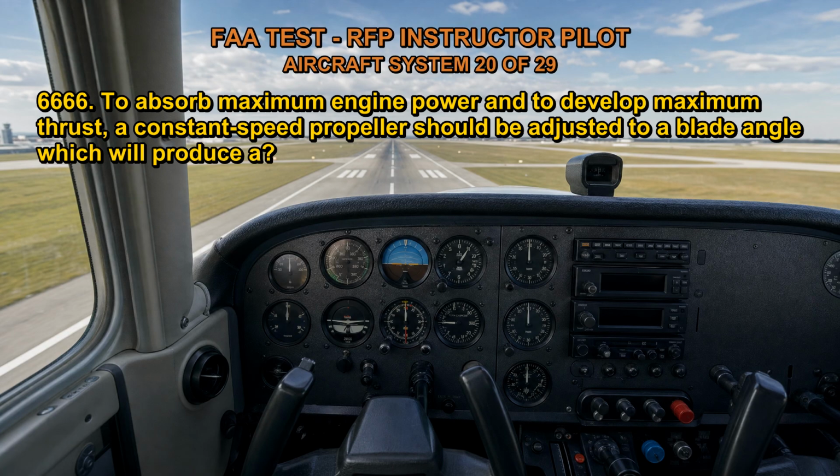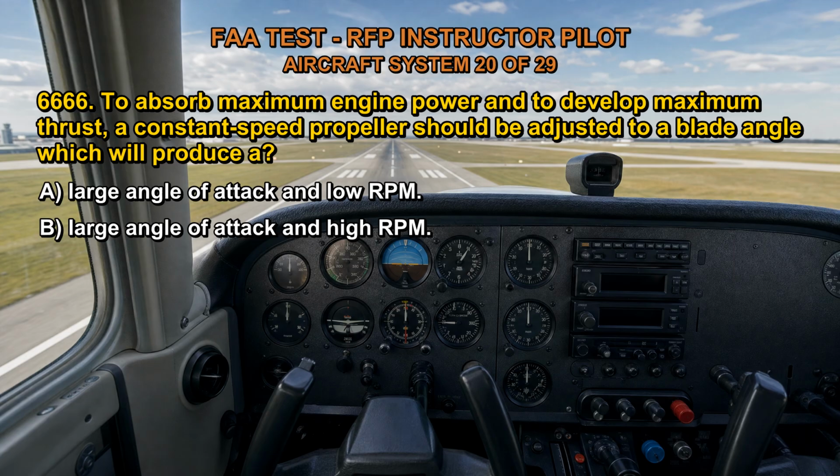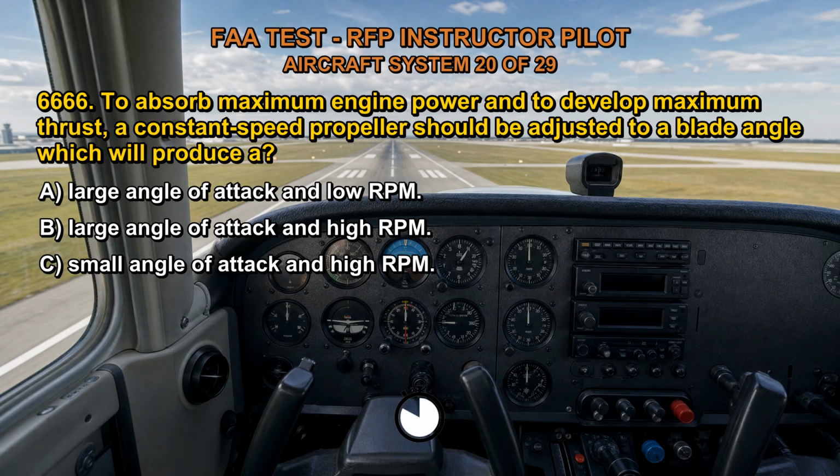6666. To absorb maximum engine power and to develop maximum thrust, a constant speed propeller should be adjusted to a blade angle which will produce: A. Large angle of attack and low RPM. B. Large angle of attack and high RPM. C. Small angle of attack and high RPM. The correct answer is C.